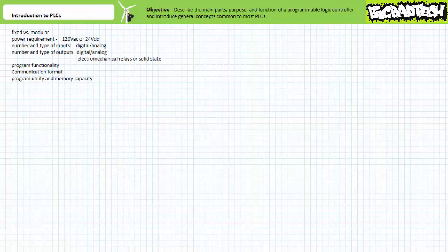There are a number of different, confusing schemes used to classify PLCs. However, I split them into two very large general categories. PLCs can either be fixed or modular. Small-sized, basic fixed PLCs are often self-contained standalone units, sometimes incorporating the power supply, input and output modules, CPU, and any communication ports into one integrated package. These devices may or may not be expandable with expansion modules. Small-sized, basic fixed PLCs are ordinarily very inexpensive, however limited in functionality, and are best suited for less complex applications.